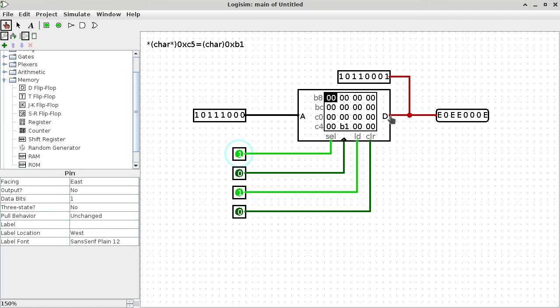But at the same time, the input pin, let me point out which input pin because there are two. This input pin here is saying, oh, wait. You and I are connected to the same node, but somebody told me this node here is supposed to be 10110001. Is that okay? So they disagree. They disagree on certain locations. Because if you look at all the bits that are zeros, there's an agreement.